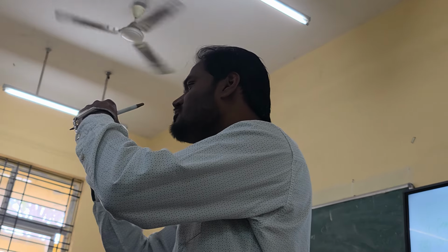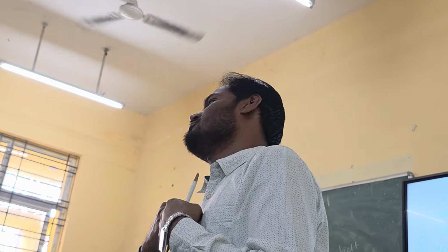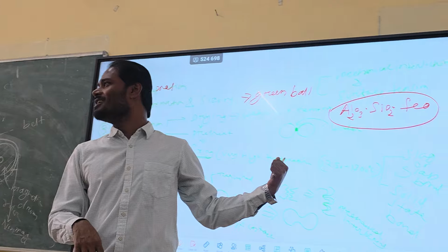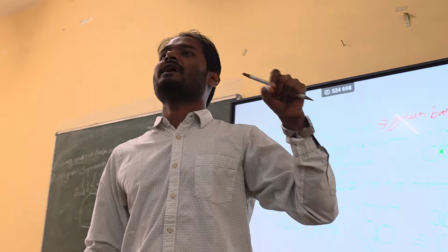That lies between the solid particles, and upon cooling, a bond will form between them. That is called slag bond or glass bond. Glass bond means it is glassy in nature, amorphous, not crystalline. This solid state bond is a crystalline bond, but this one is a glass bond or slag bond due to the presence of slag.